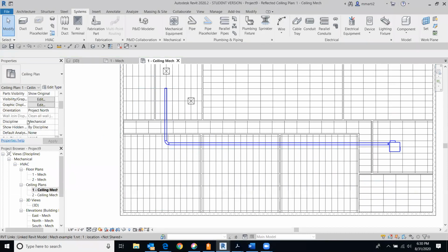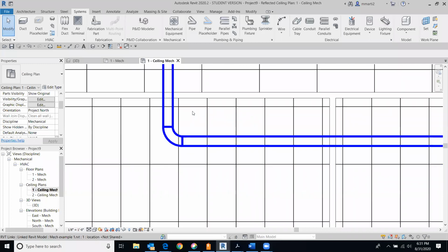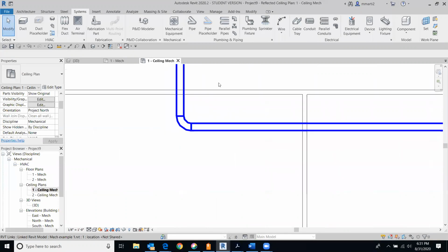The difference between the ductworks when we've selected them is the determining factor is these joints. It's always best to have a smooth joint corner where it comes like this. If it comes to more of a point, the air doesn't flow as well, and there's all sorts of aerodynamics that are involved in that. Whoever you end up working for will tell you which type of duct that they would want to use, but we default to this one just because it is a more air efficient duct work to use.